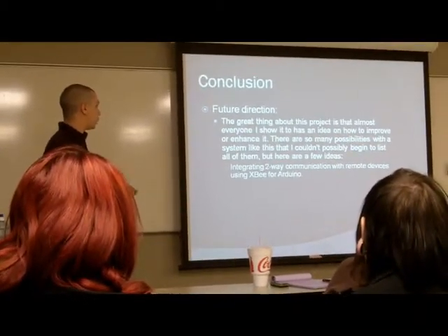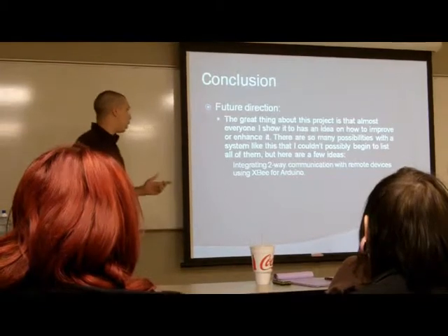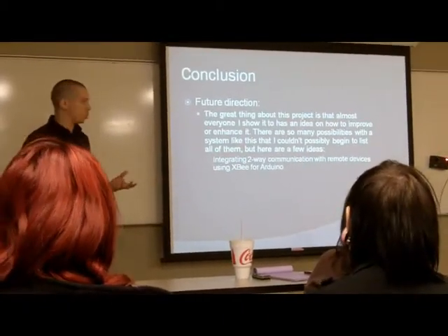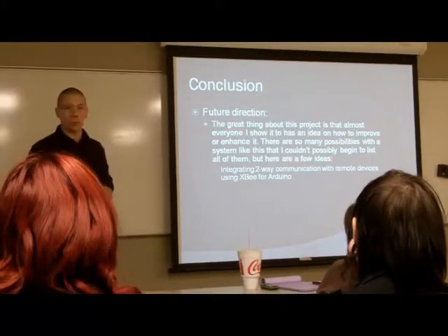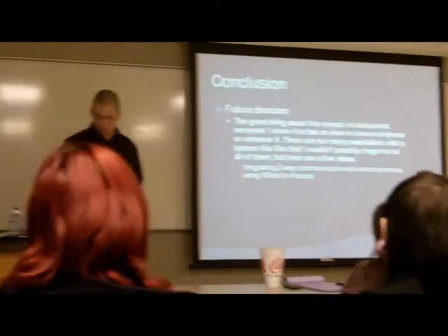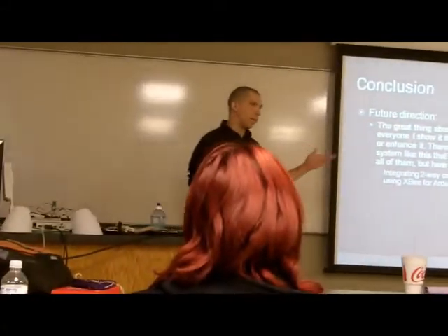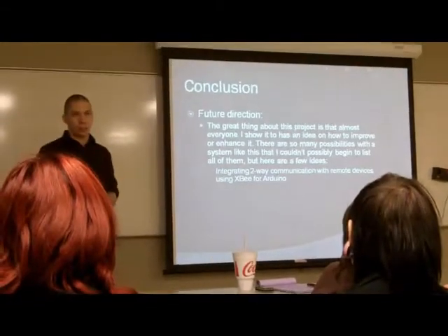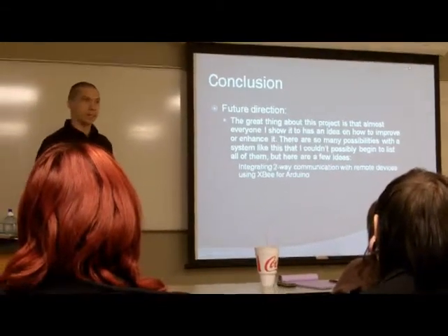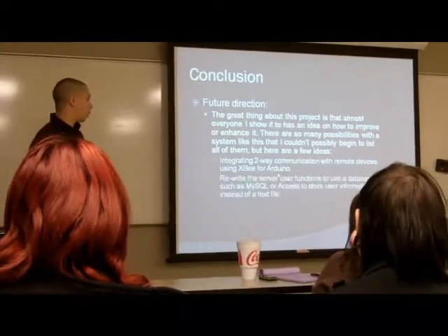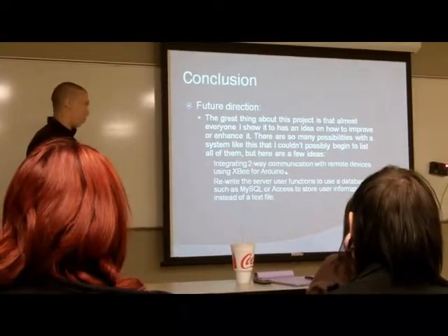Some things I'd like to do is integrating two-way communication using XBee, which is a wireless communication module that allows these microcontrollers to talk to each other wirelessly. Right now, it's just one-way communication. I give it a command, it does it. But I don't know that it's actually received it and done it. So it doesn't get feedback to the server to say, yes, the door is locked or unlocked. But it's really complicated and I couldn't get it working in time.